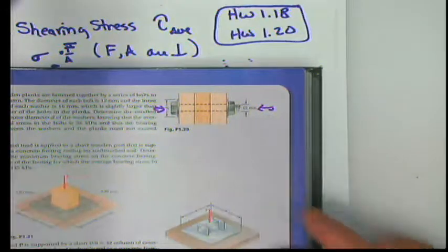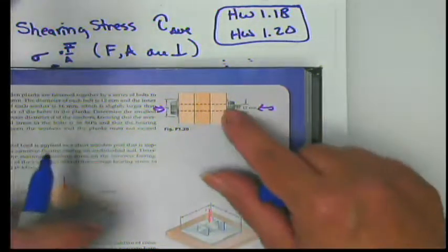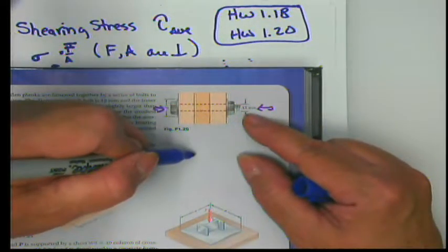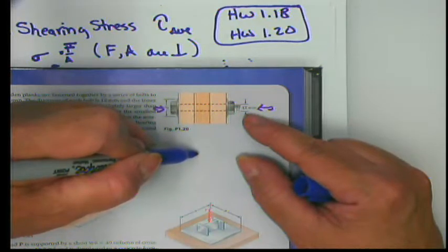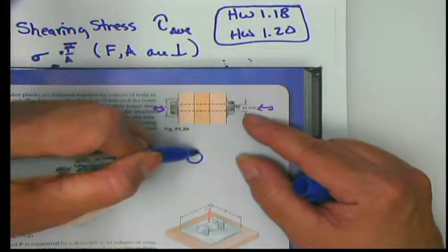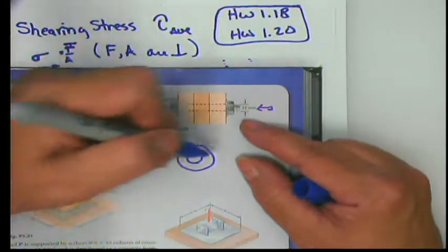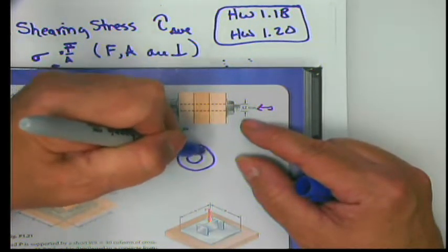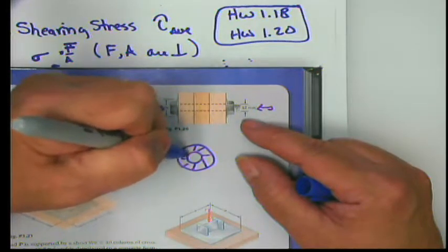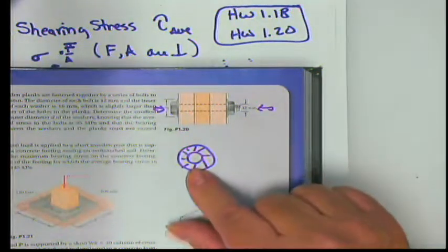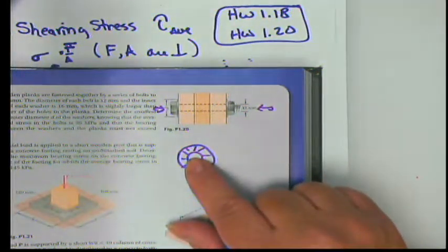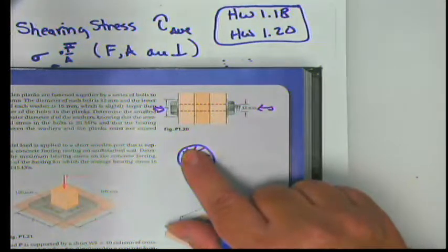It's a little bit more complicated when we talk about the bearing stress. If you look at the hole that the bolt makes and the washer around it, if it fails in a bearing stress situation, this is the area that's going to absorb it. Whatever is in the center is not going to hold on to that. This isn't really a shearing stress.